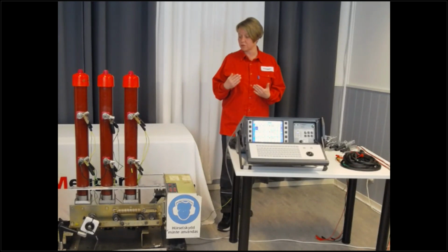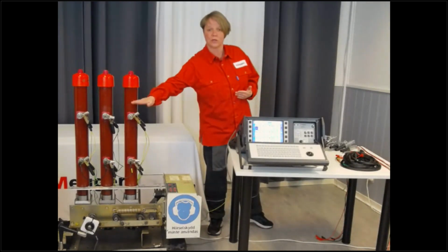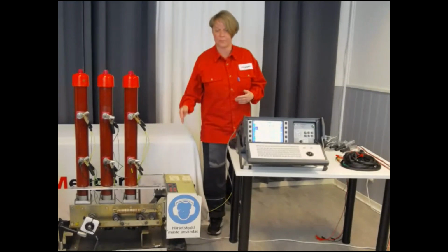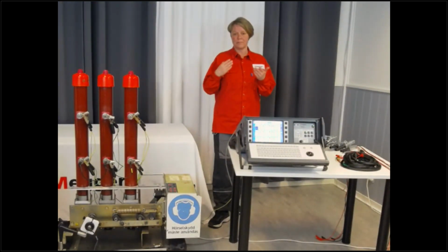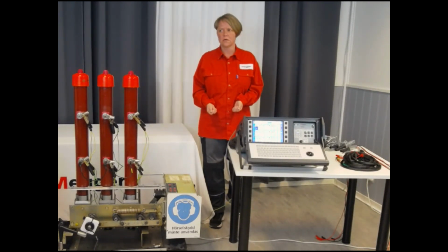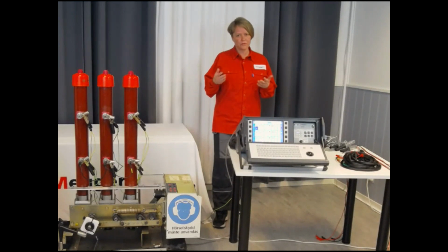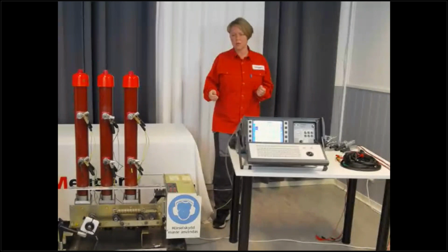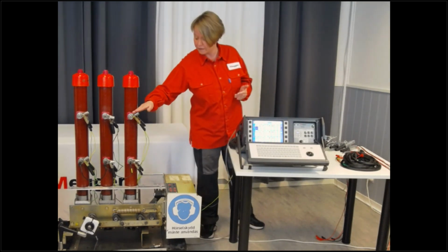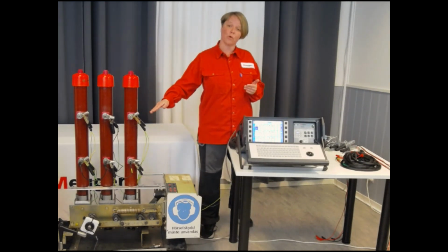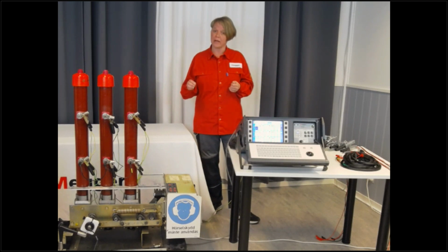Another important thing to know is that you should always connect at the breaking point, at the pole. When people hear dual ground, they think, oh, then I can connect at ground. If you're experienced, maybe you will manage this because you know how to put the grounds. But for any normal user, and especially for beginners, always connect close to the break point. That's really, really recommended.